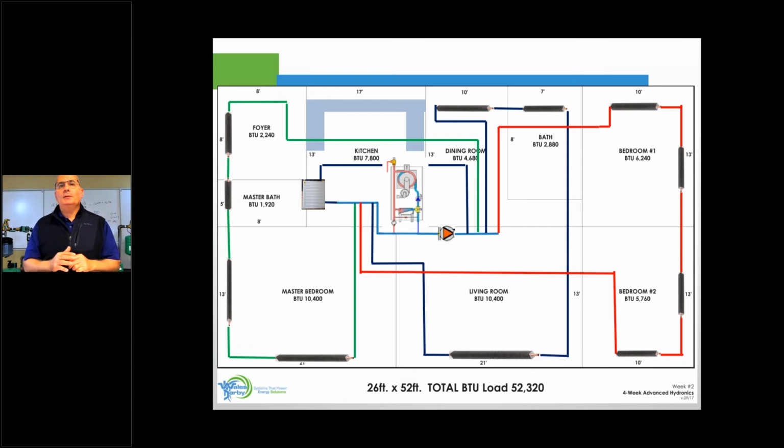100-foot run is a very common loop length. Most of the time when contractors call myself, John, or Anthony, or Rick, or Rob from our CSG group, they're asking us to help them decide a circulator: what's your longest loop? And it starts off at about, I'm going across the house, I'm up and down, and I'm 50, 60, 70, 80, it's about 90, call it 100. It's always 100. So if we do a 100-foot loop times 1.5 times 0.04, you should get 6. So that's the magic number to know. 100 foot equals 6. Why?